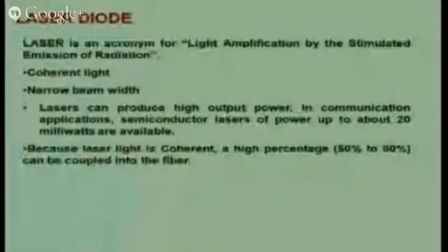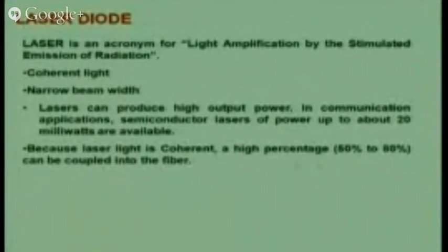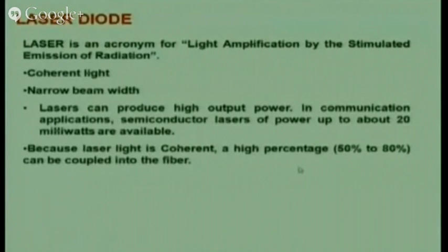It can produce high power output in communication applications. Lasers up to 20 milliwatts or more are available, and because it is coherent, the percentage of light which I can couple is around 50 to 80%. So 50 or 80% is still much more as compared to my LED case.